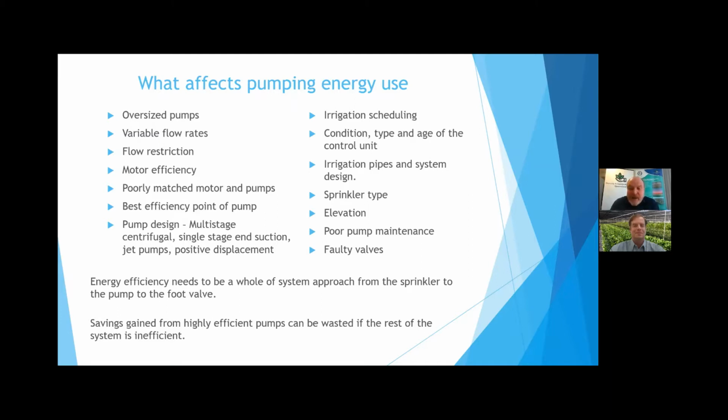Energy efficiency and pumping efficiency must consider the whole system, as each component within the system will actually affect the overall efficiency of that system. In some cases, the efficiency of a small component may be insignificant, but the efficiency or inefficiency of that component, and each component, will or could cancel out the benefits of installing a highly efficient pump.